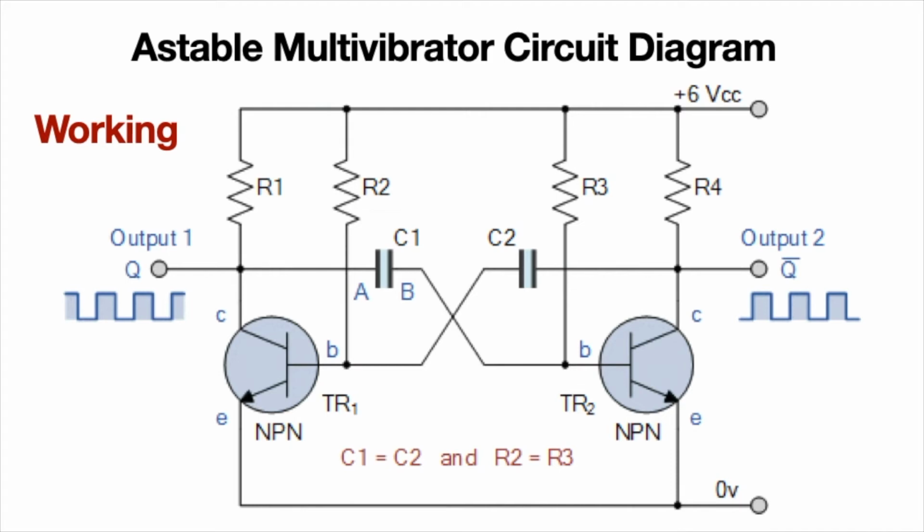Now the capacitor C1 might have accumulated some charge on it, right? So as transistor Q1 is short, the left hand side of the capacitor will be grounded, and therefore the negative voltage will appear at transistor Q2, and Q2 will be in the cutoff region.